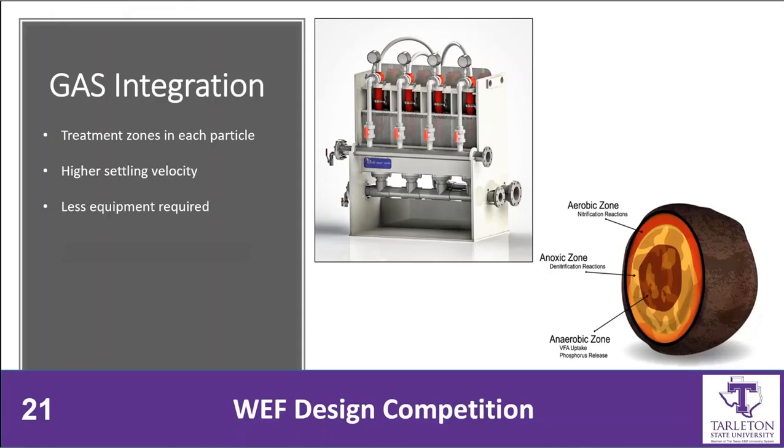This allows the sludge to granulate over time, and each granule develops its own A2O treatment zones, as shown in the figure on the bottom right. Not only does this amplify the treatment capacity of the activated sludge process, but the dense sludge settles exceptionally well when compared to normal sludge. Perhaps the most attractive characteristic of this alternative, implementing granular sludge for 10 mgd of average flow requires only a small assembly of 2 hydrocyclones, about half the size of the skid in the top left picture.